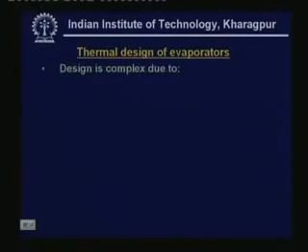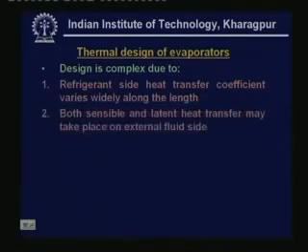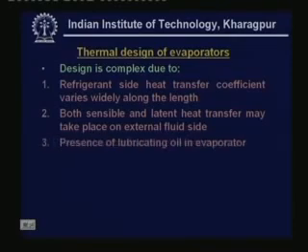I will not really go into the details of the exact design of evaporators, which you will normally study in an advanced course. I will simply explain the basic principles and the complexities to be considered while designing the evaporator. First let us look at the complexities. The design is complex because the refrigerant side heat transfer coefficient varies widely along the length. Both sensible and latent heat transfer may take place on the external fluid side, as I have already told.